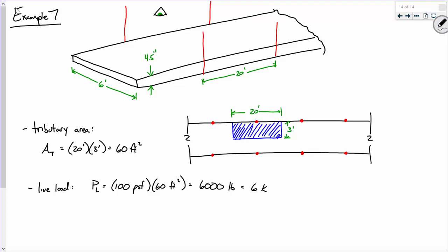All right. Is there anything else that rod has to support, though? That's a good point. It does have to support its own self-weight. Ultimately, though, the actual weight of the rod is somewhat negligible. When we're talking about a rod that's only yay big and maybe, I don't know, 12 foot tall or something like that, it's heavy, but it's in no way, shape, or form comparable to what? The slab. The slab is going to be much heavier.